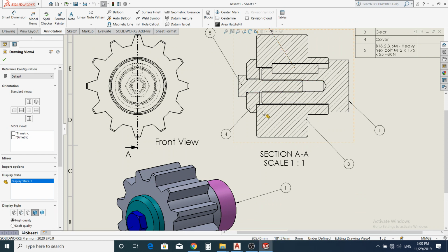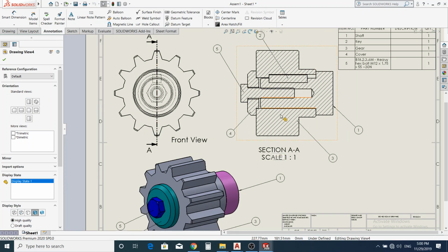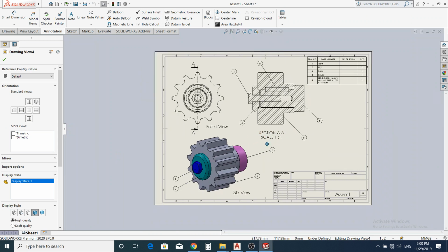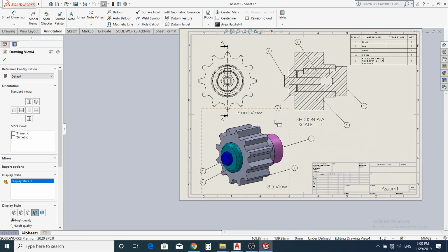But because it is dismountable, I just have to unscrew this screw, remove my cover, and pull out the gear, and then the key will be left there. I will just have to remove it, machine another key, and replace it. So by far, this is the best configuration we can use to secure this spare gear onto the shaft.